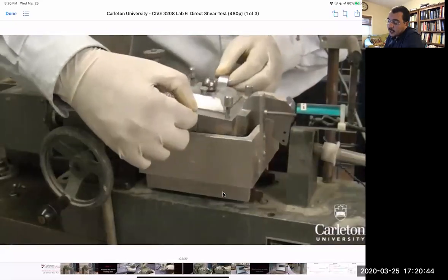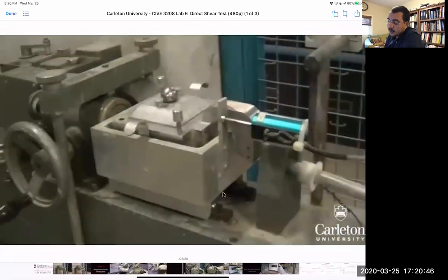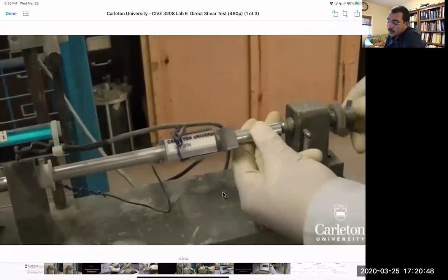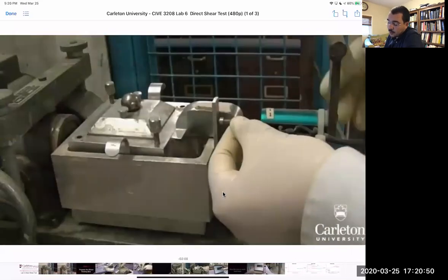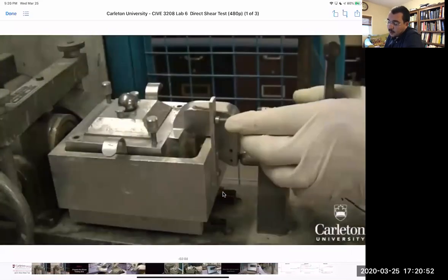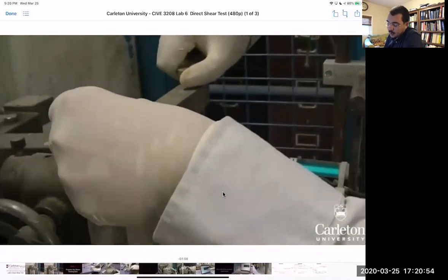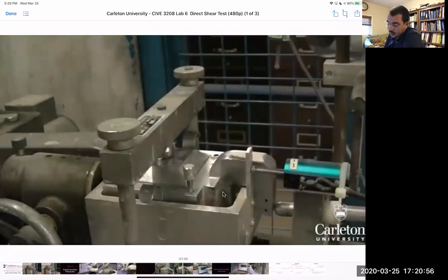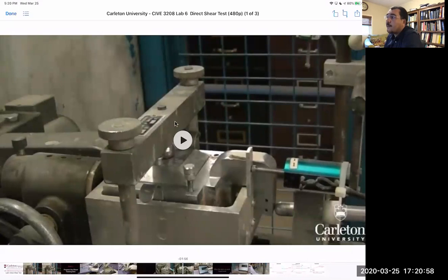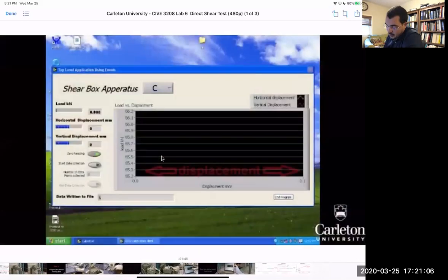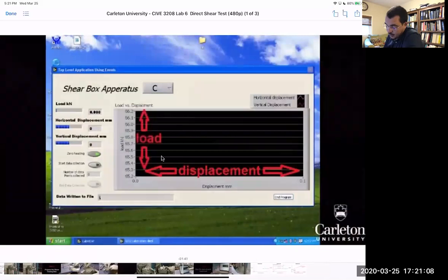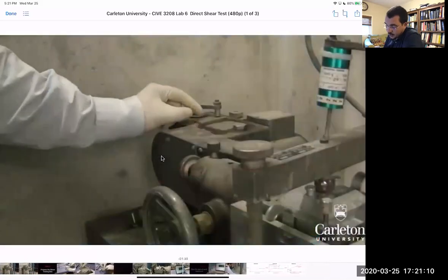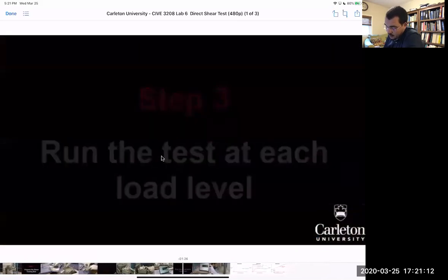And basically he'll place it in here, and that's the transducer in the horizontal direction. This is the jig that applies the load. So the load goes from this bar to this steel ball, then into the sample, and that's the displacement or strain changing with the load.